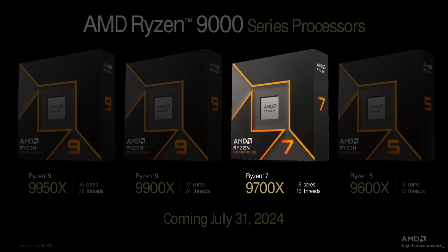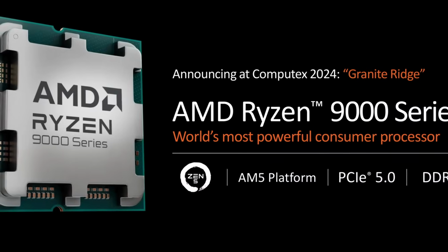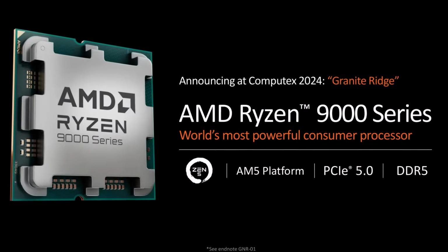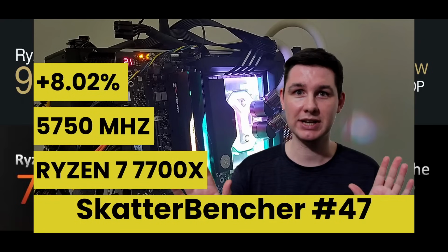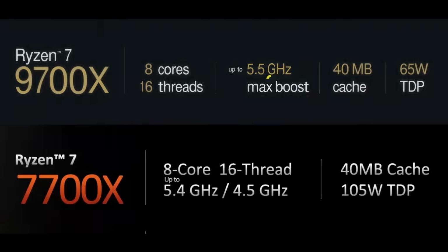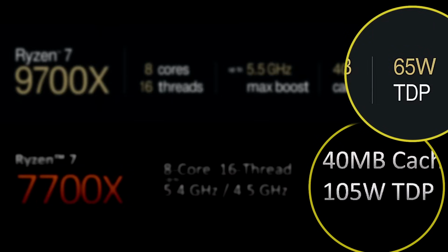The AMD Ryzen 7 9700X is part of AMD's Zen 5 based Ryzen 9000 desktop processor product line, codenamed Granite Ridge. The Granite Ridge processors were introduced on June 2, 2024 during Computex 2024. The Ryzen 7 9700X succeeds the 8-core Zen 4 Ryzen 7 7700X, which we overclocked in SkatterBencher number 47. It has a base clock of 3.8 GHz and a listed boost frequency of up to 5.5 GHz. Unlike its predecessor, the TDP is capped at 65 watt.